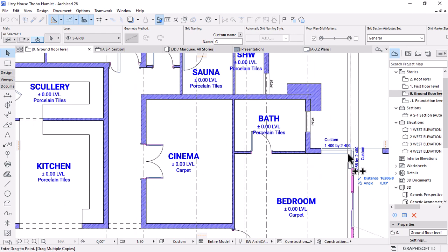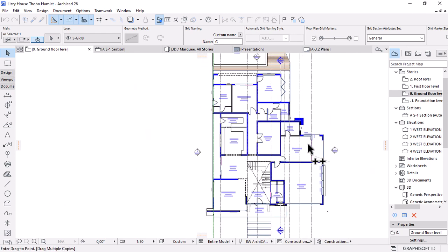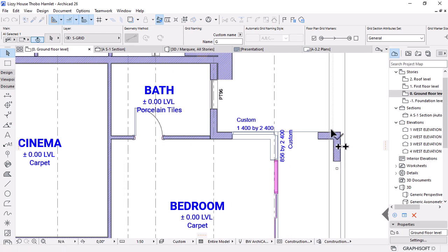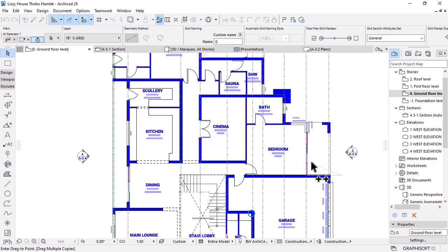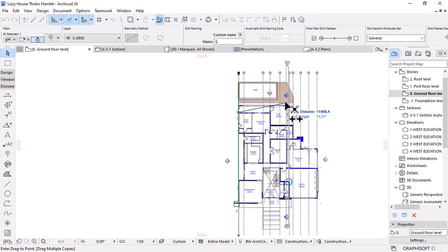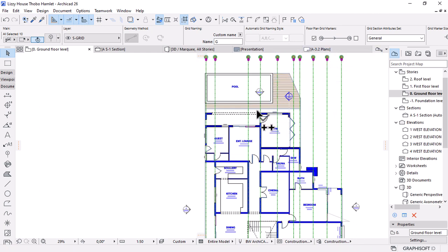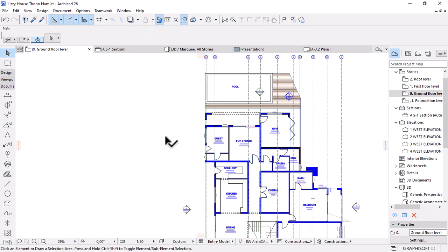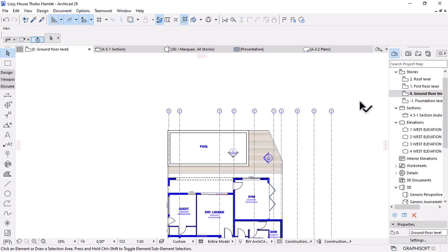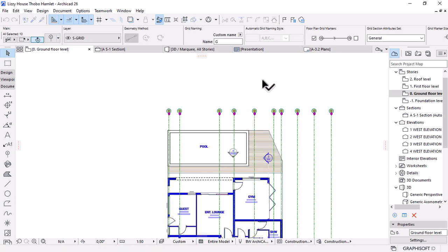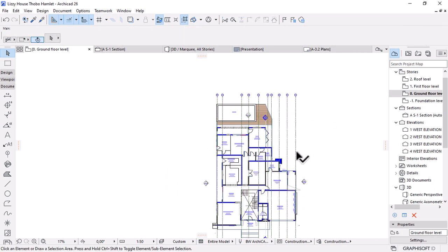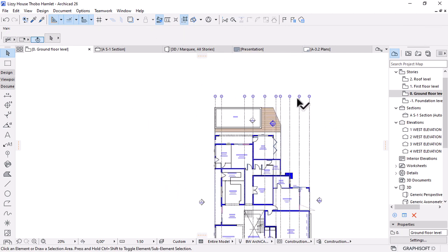Grids are very important, especially in construction, when the project is in construction, because that's what the engineer and the contractors are using to reference, or even to do some calculations on getting some dimensions on the site, especially where there is no such information in your drawing. So it makes their life easier instead of requesting information. It also helps you again. So yeah, I think I have this.